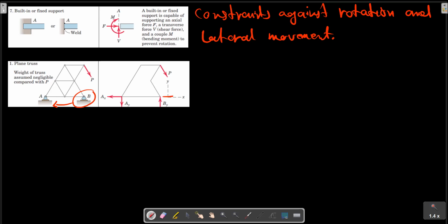After this change a force will be added here, for example Bx. The three scalar conditions of equilibrium in this equation will not now provide sufficient information to determine all four unknowns, since Ax and Bx could not be solved for separately.